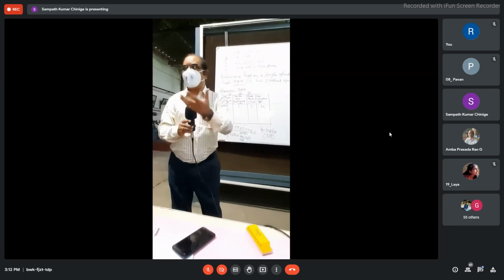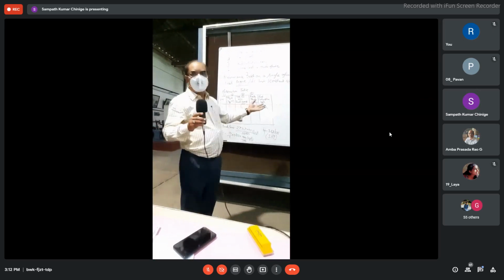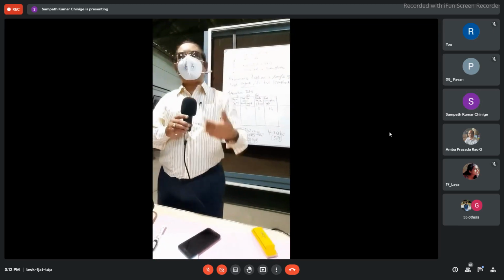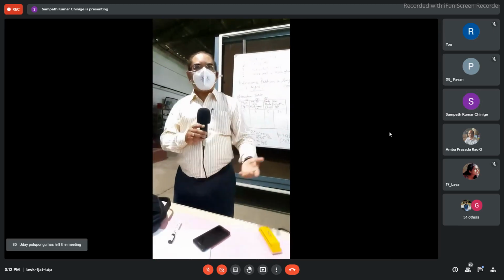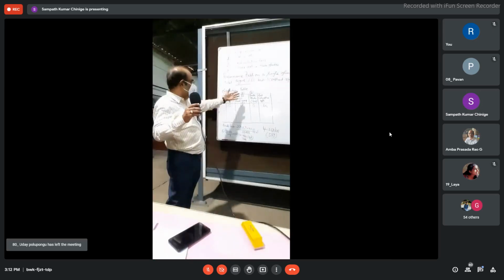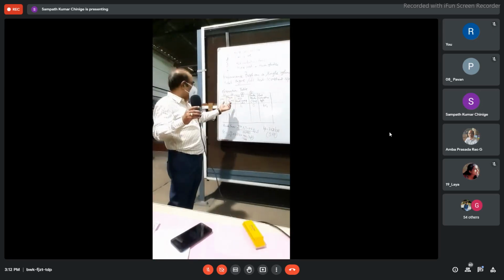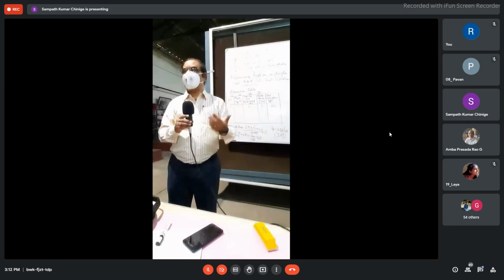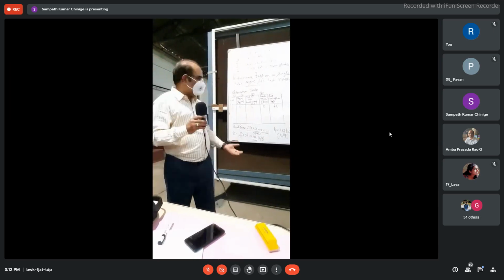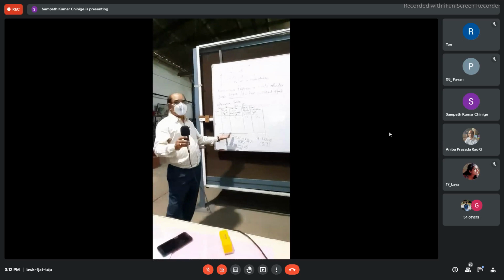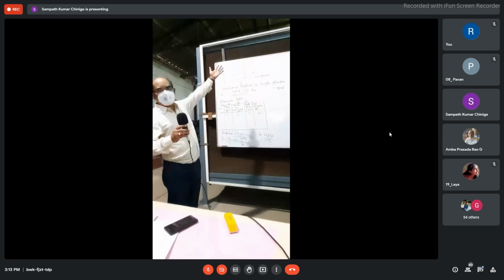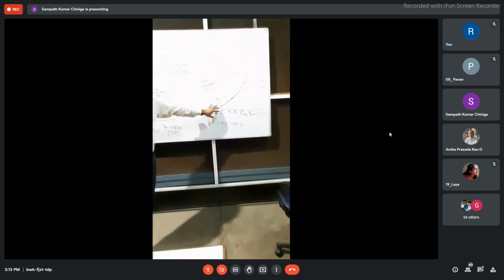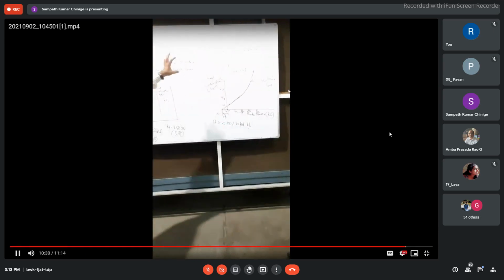So note down that value and calculate the brake force. Again, go to 1100 rpm and note down the torque meter reading. Go to 1200 rpm and note down the torque meter reading. As you go up in speed, record the speed versus the torque meter reading. At 1000 rpm, what is the torque? At 1100 rpm, what is the torque? 1200, likewise, you go up to 1500 rpm, because we have a value at 1500 rpm which is given by our Willans line method. Whatever value we obtained from the fuel consumption method should be equal to the motoring test method.